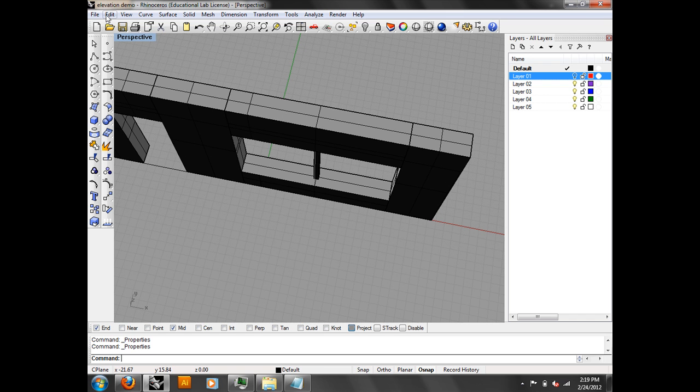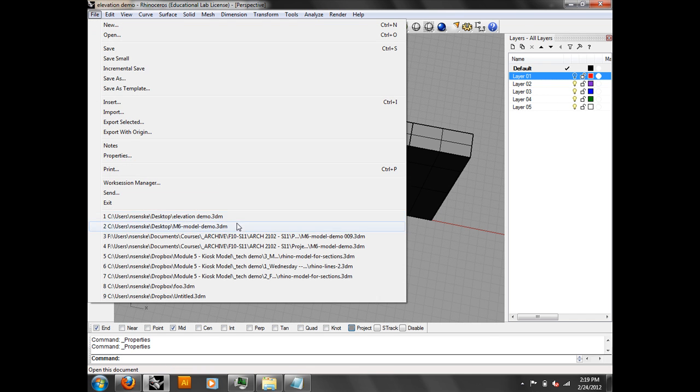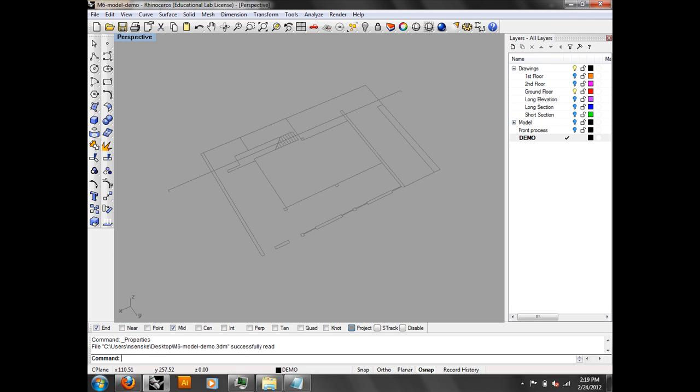I'm going to show you using Thomas's model. I just want to quickly run through this process. Again, you would take all your drawings from AutoCAD, like in your kiosk model, and arrange them with each other, and export them to a DWG that's an old DWG, like an AutoCAD 2000 or a DXF, of a very old vintage, so that you don't miss any information. Open that up inside of Rhino, making sure to pay attention to the scale of that file. Then you start arranging your scaffold.